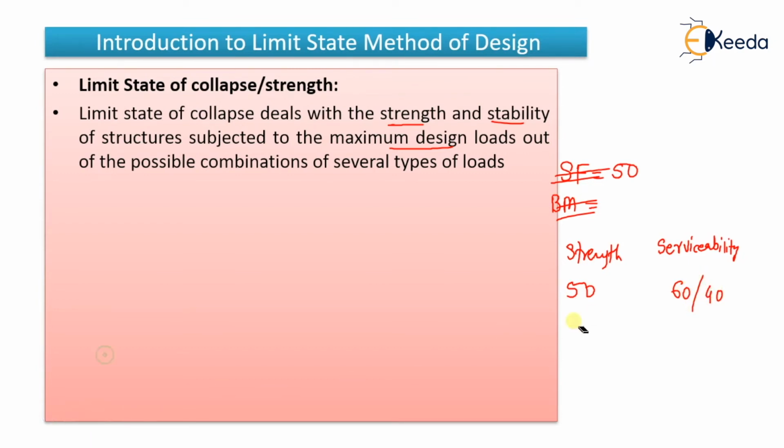So what is my concern now, what will I tell? So you will design it for 50 load or 40 load. You can pause the video and think on that. You will have to design it for 50 load, because load should be taken as maximum. Load you will take as maximum, and strength you will take as minimum. Clear? So this is your safe design.